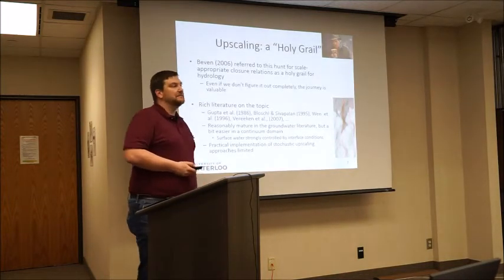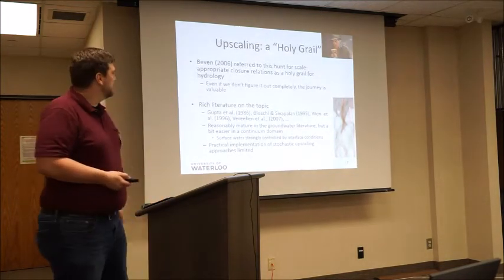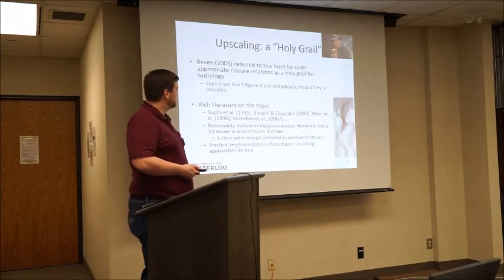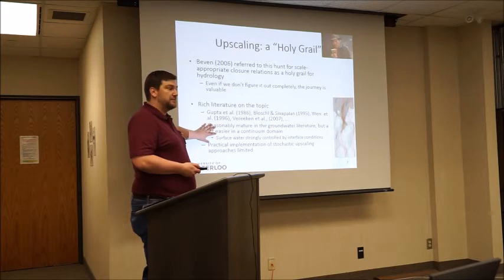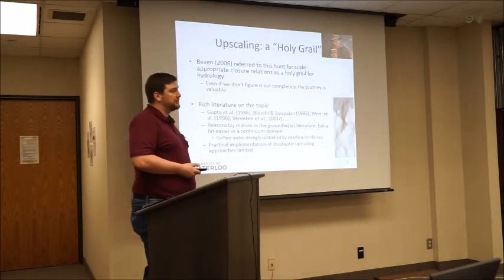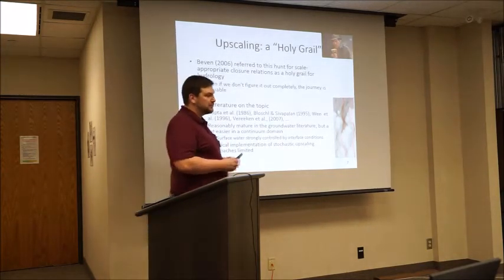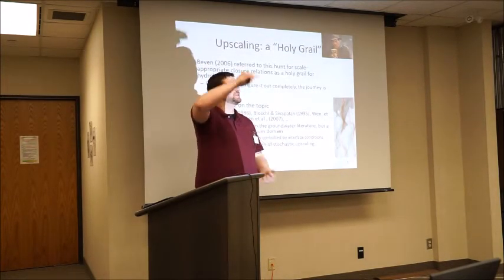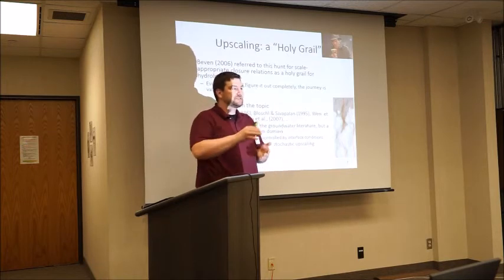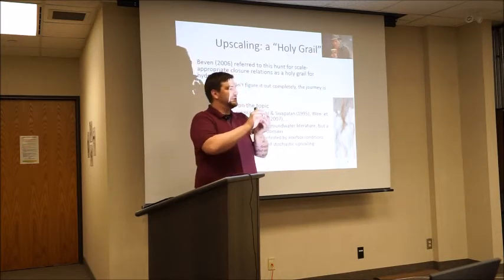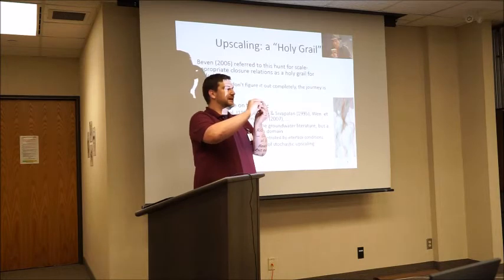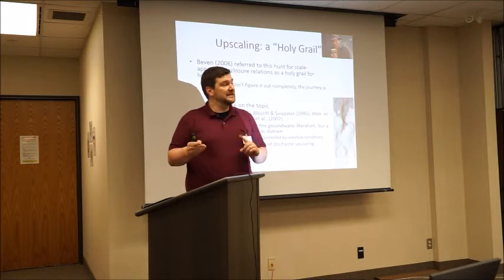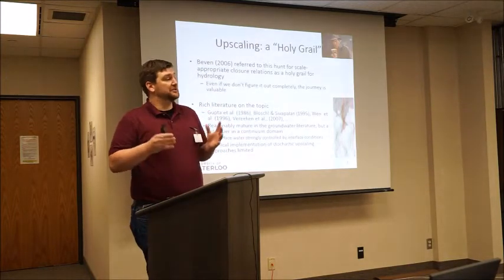There's an extensive amount of literature on the topic of upscaling. This is a handful of scores and scores of useful and interesting papers. The approach is actually pretty sophisticated in the groundwater literature, and the reason for this is because we can take a parcel of groundwater and imagine it extends out in infinite directions, and there's no influence of boundary conditions, and no influence of interfaces, and we can treat that as a statistical description that extends out in all directions. And once you do that, you can do some very neat things mathematically to get closure relationships at large scales.